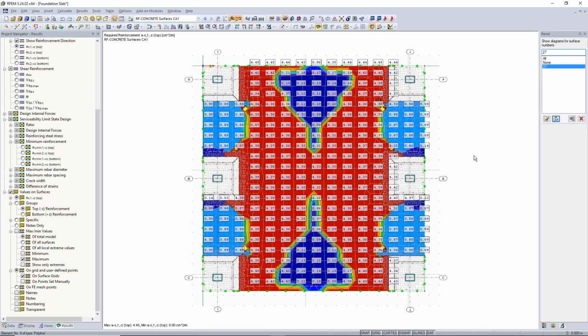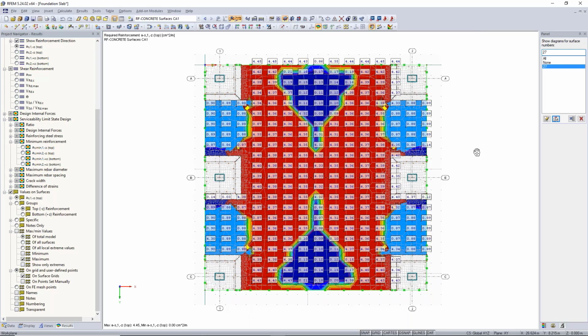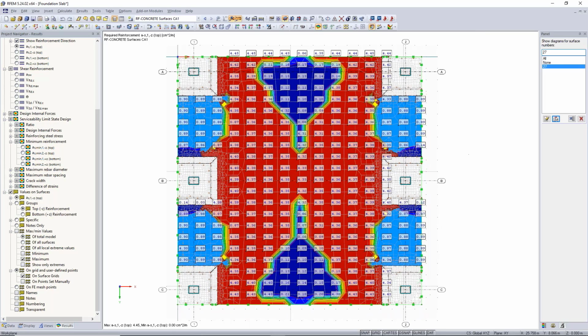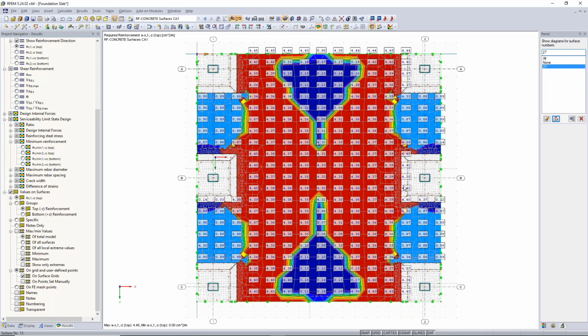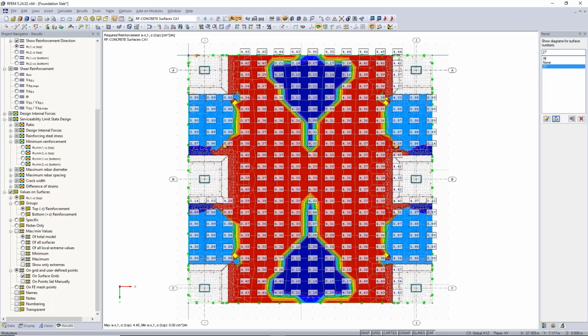Before I print this graphic into the printout report, I could also think about how I could save a little bit of color for printing. Therefore, I would like to switch from this filled graphical view with isobands to isolines, and that is hidden here. You find this option here, isoband.